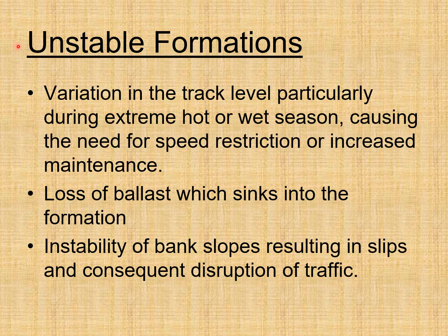Unstable formations. Variation in the track level, particularly during extreme hot or wet season, causing the need for speed restriction or increased maintenance. Loss of ballast which sinks into the formation. Instability of bank slopes resulting in slips and consequent disruption of traffic.